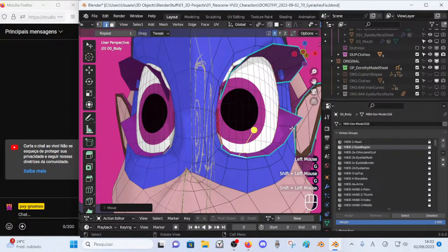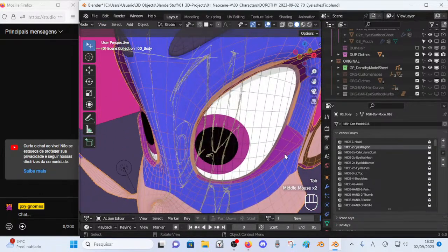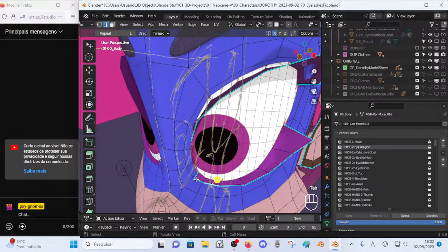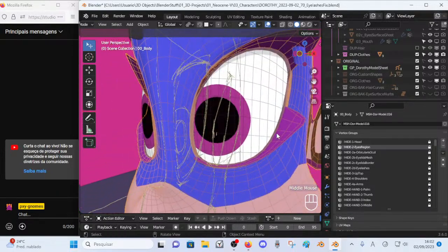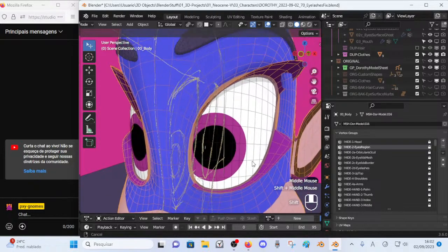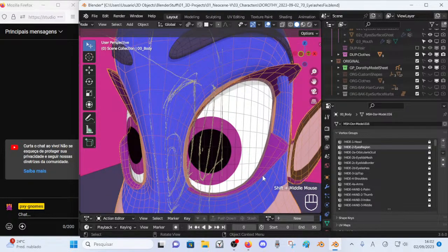It's just a single edge ring and this edge loop, and that does the job for the rig that I have here. So even dynamic motion of this, of course there are subdivisions, but they will share the same weights of the original vertices. So yes, this is looking good.